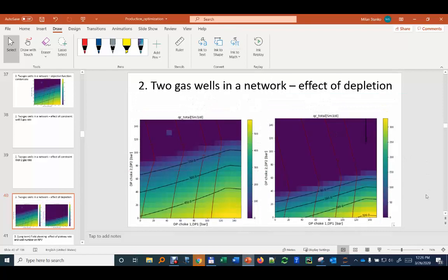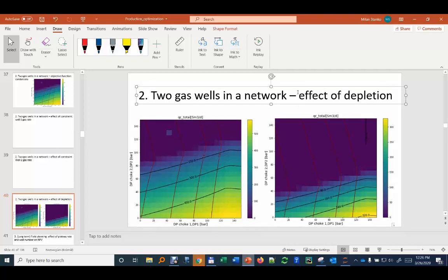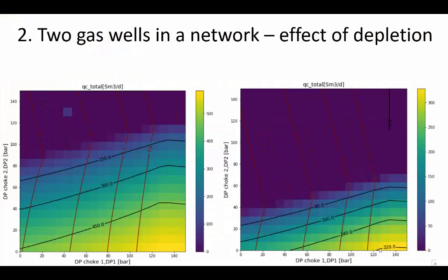But the one to the right, this PR2 was, I think, like 210 bar, while PR2 here is 150 bar. So you see in that case it simply shrank, and the condensate that you get is not as high, it's not almost 600, but it's actually closer to 325. But essentially the location of the maximum point didn't change much. Okay, bye.